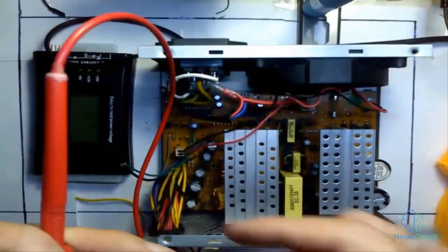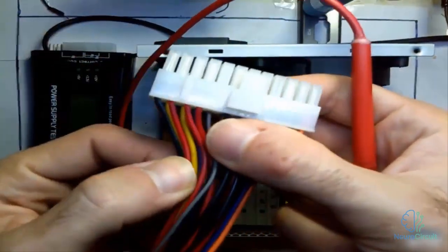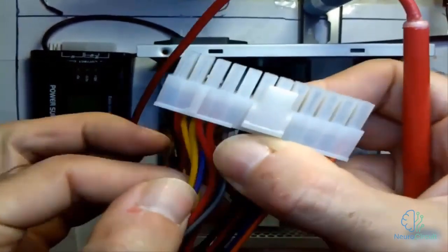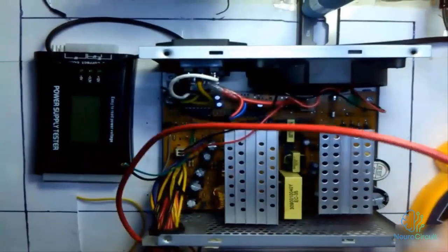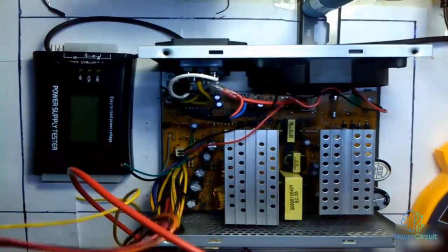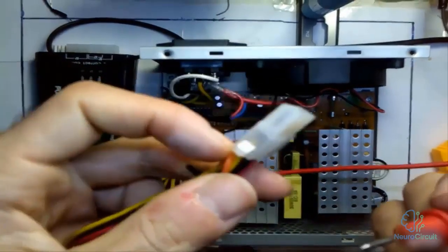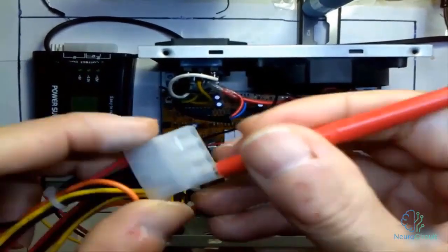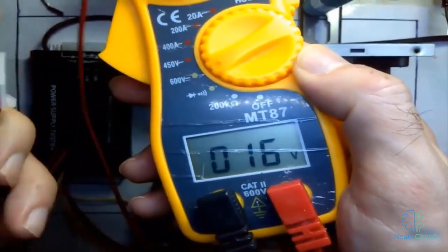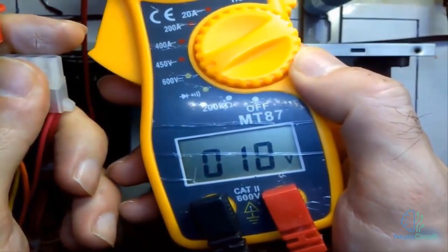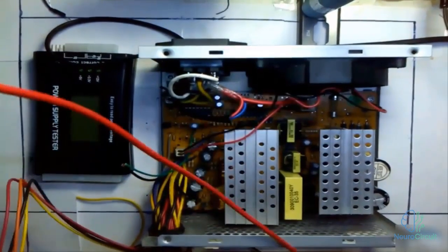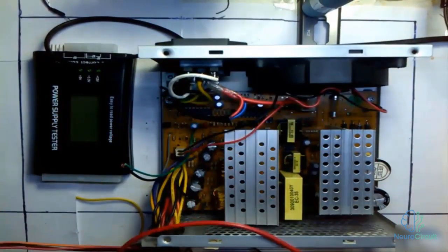Okay, now I'm going to test the 12 volt wire, which is the yellow wire. I bring the yellow wire here. I can even use the next pin, which actually makes the test easier for me, as you can see. Here I connect the positive lead to the yellow wire, and you can see the result here. Well, the 12 volt positive is also fluctuating, meaning that in terms of output voltage, this power supply doesn't have a suitable voltage at all.